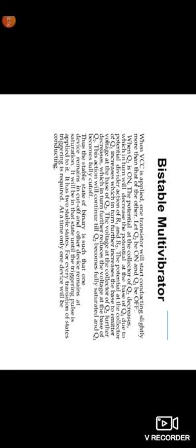When Q2 is on, the potential at the collector of Q2 decreases. Q2 is on means it acts as a closed switch, and it will decrease the potential at the base of Q1 due to the potential divider action of R1 and R2.